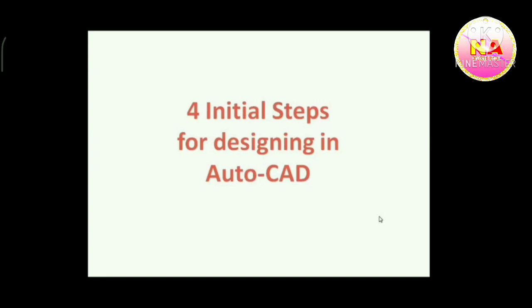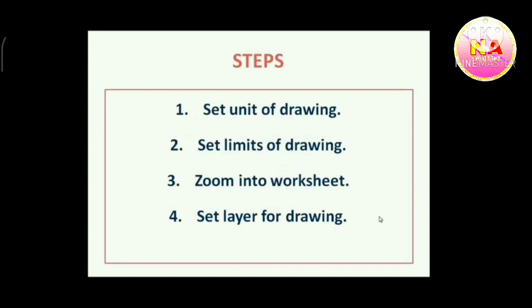Basic initial steps that you must do before starting designing in AutoCAD. First, let's see what those steps are. These are the 4 steps that you must follow before starting a drawing in AutoCAD. First step says set unit of a drawing. Here we set a unit of our drawing, like mm. We want to draw in mm or inches.